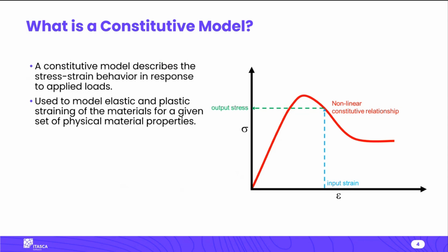And then there will be some sort of failure or other behavior occurring when you reach some stress state. And then what happens at that point is really specific to the constitutive model. Often these things are interestingly nonlinear, and all kinds of interesting things can happen at or beyond the failure point, depending again on the constitutive model and the properties that you set.